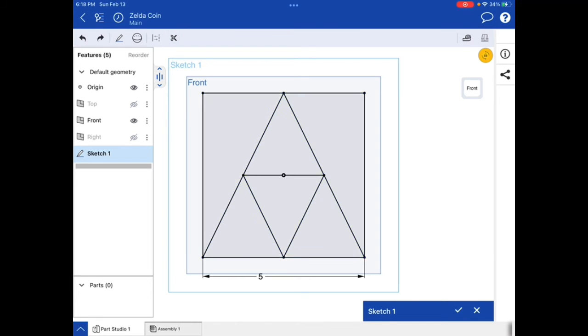If you trim one of those entities, it's going to undefine the sketch. And we don't want the undefining, you know? So we want those 2 gone, right? Those 2 are our goal. So we're going to select those 3 lines, open up our sketch tools, or just make it into a construction line, so it's one solid entity, and we're gonna finish the sketch eventually.